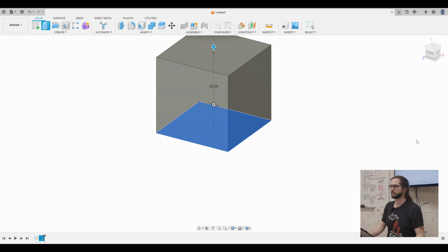And is all this menu there at the top? So this side menu pops up when you are in the middle of doing an extrude. So when you click that extrude button, and then click your drawing, it's going to pop up that menu. It starts on the right side, but you can move it around if you want to. Now, if you're going to do a function other than the new body, is that built in this same space? Yeah, so you'll draw it and extrude it the same way, and we'll get there.